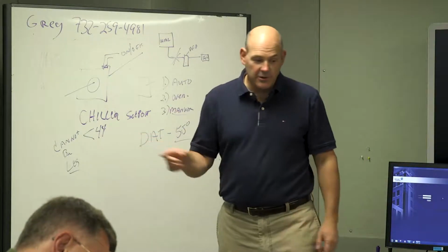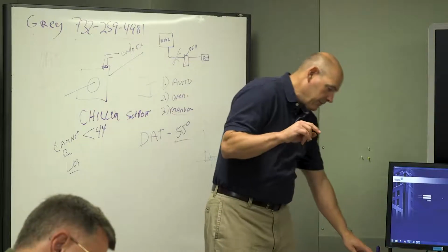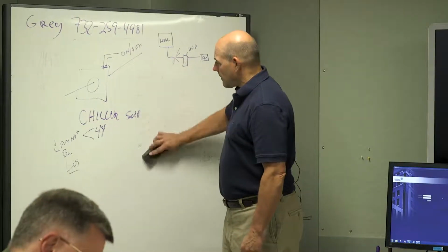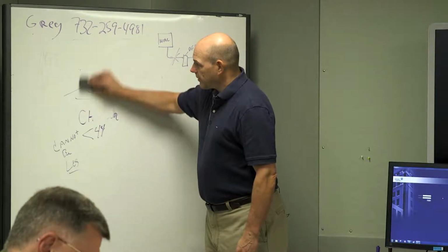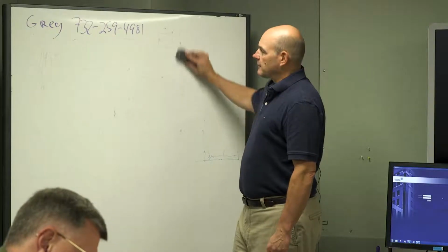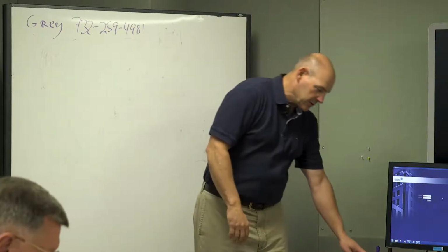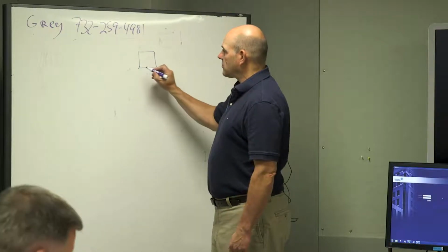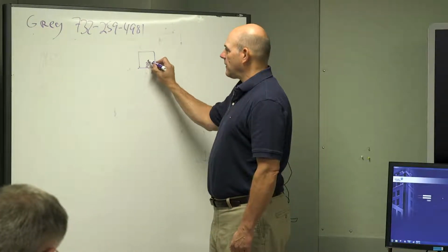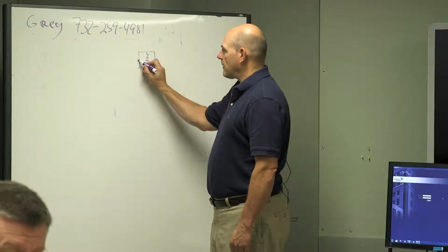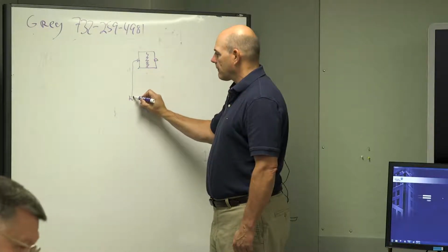But, and this is critical, a differential pressure sensor works on 2 copper tubes. Again, when we walk through the field, I'll show you. You have the transmitter here, and the transmitter just has a little tiny diaphragm in between. There's an input on this side and an input on this side, and it's a copper tube.